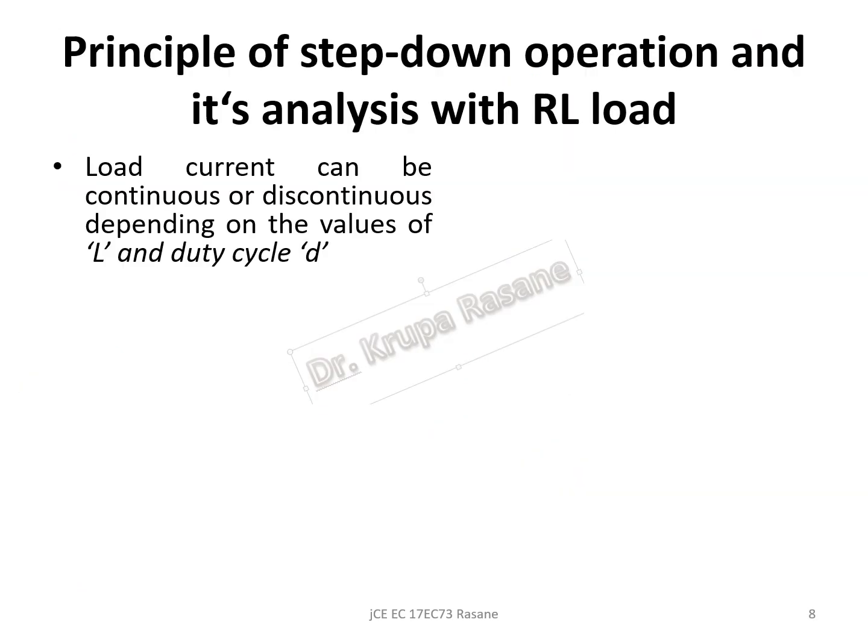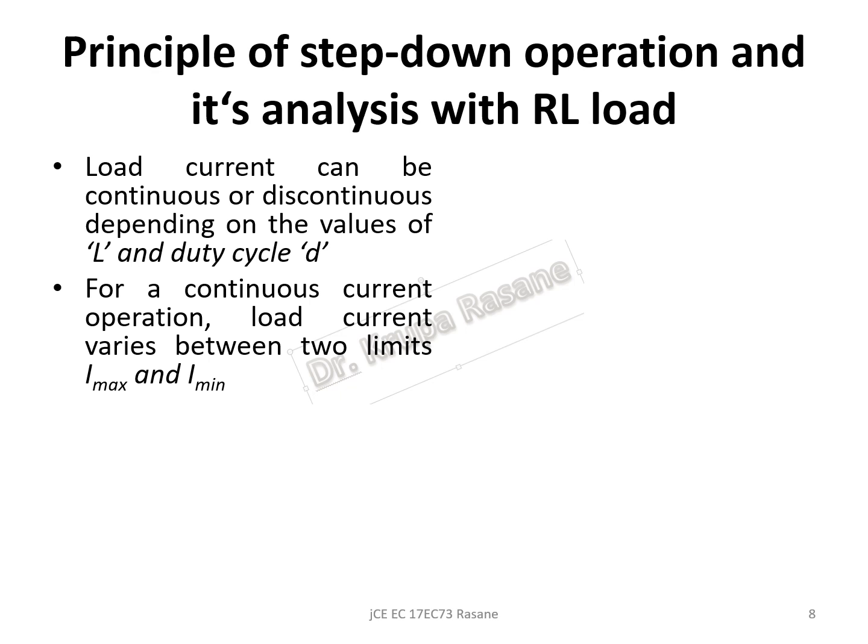So coming again to the analysis, the load current can be continuous or discontinuous depending on the value of L and also the duty cycle D. In some books the duty cycle is represented as K. In Rashid he has used it as K, but since I am using D throughout the video, I'll keep it as D. So what is duty cycle? T on upon the total time T, where total time is equal to T on plus T off.